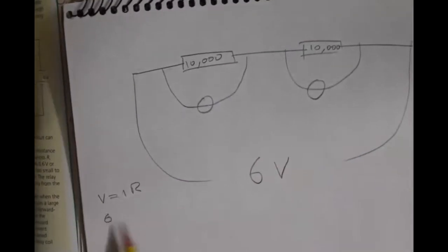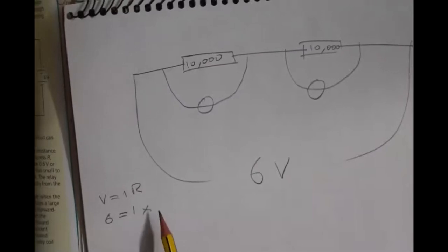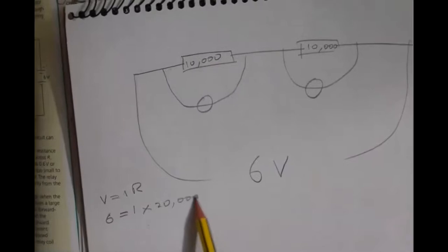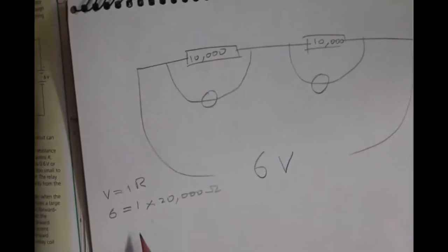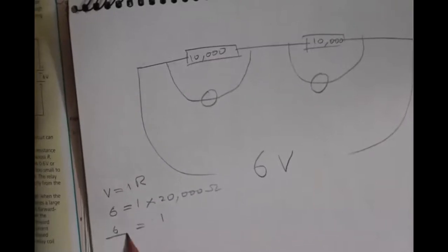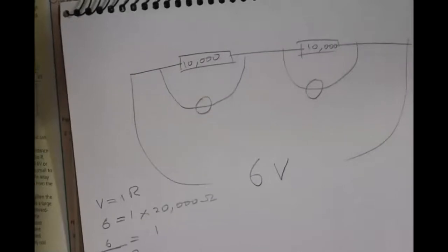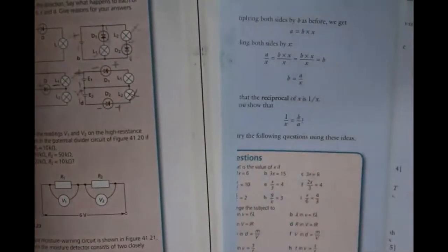So we're gonna put 6 in. The current we don't know. And the combined resistance is gonna be 20,000 ohm. I hope everybody remembers how to add the resistances when the resistors are connected in series. We just add them simply, right? That was done in basic.